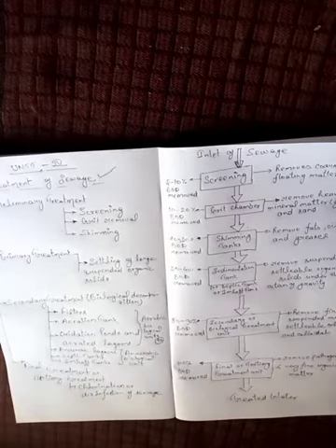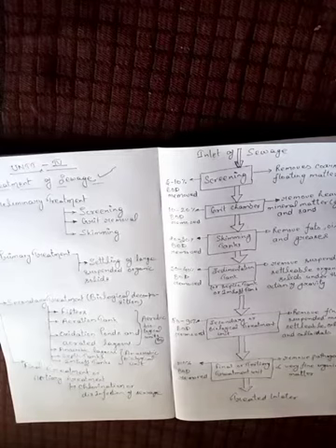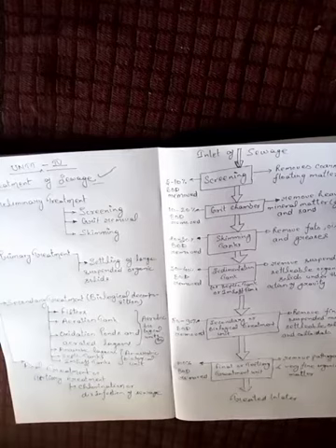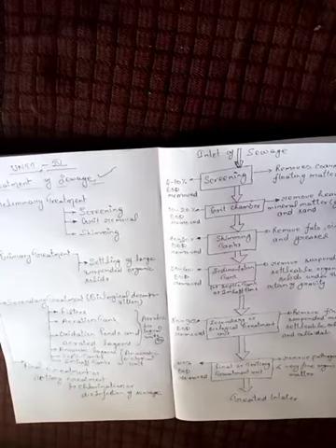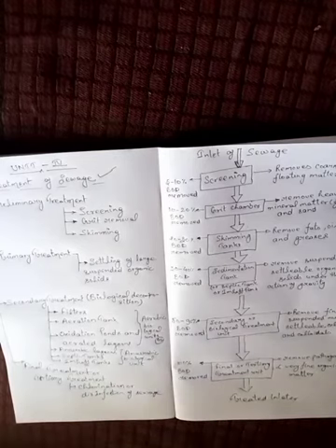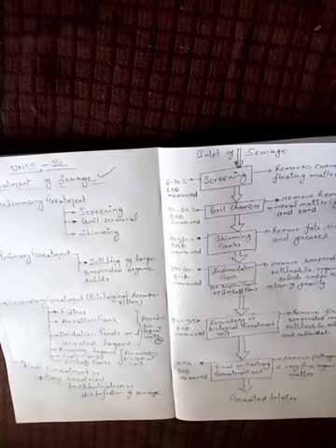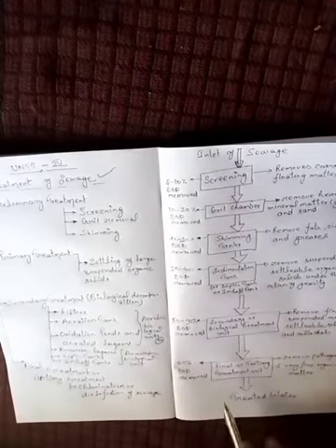Sewage is stored in rectangular or various other types of tanks in which the velocity of the flow is reduced to 0.3 to 1.2 meters per second, by which the suspended particles settle down to the base of the tank under the action of gravity. In this step, 30 to 40% of the BOD is removed.